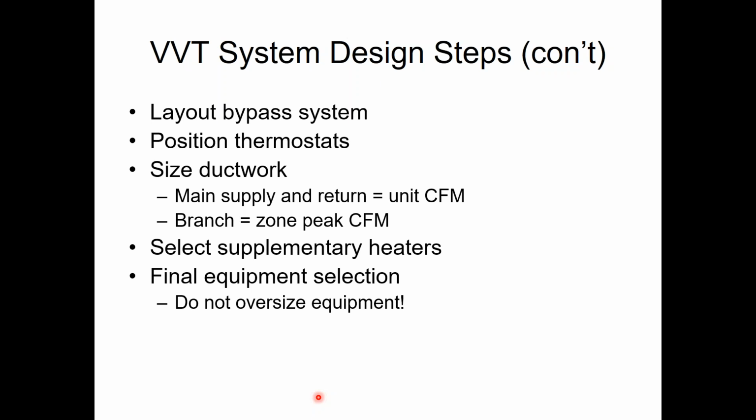Most of the systems that I've seen, you're essentially disabling second stage equipment on most of the pieces of equipment because the equipment is so badly, grossly oversized. The equipment should be smaller than if I didn't put zoning in. If you were going to put 10 tons in on a constant volume scenario, it may be 8 tons when you put a VVT in.